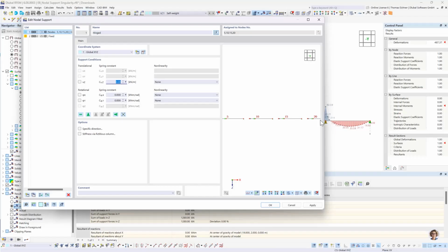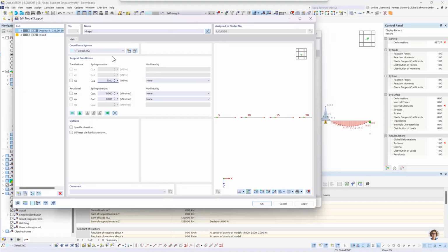I mean, it's a plate, and it has one support on the right side and one support on the left side. So we could call it statically determined. And with that said, if we add some deformation capacity of the support, it would be able to deform in that direction. But it would have to take the force anyway, because the force can't go anywhere else. That's only possible with statically overdetermined systems. That's the reason why it wouldn't help in this case.